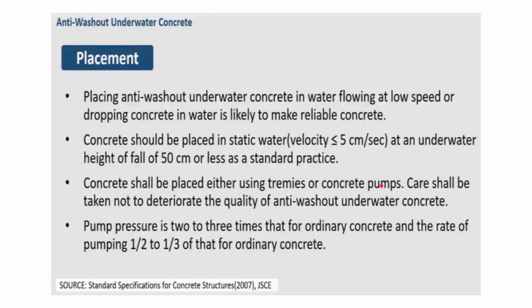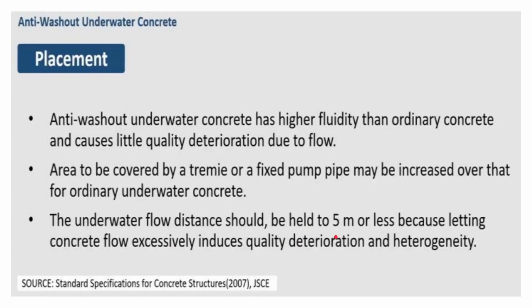As I told you, using a bucket is a very traditional way, and that is not accurate, not efficient, and does not give a quality mix. Care shall be taken not to deteriorate the quality of anti-washout underwater concrete. That's why the bucket should be avoided. Pump pressure is 2 to 3 times that for ordinary concrete, and the rate of pumping is half to 1/3 of that for ordinary concrete.